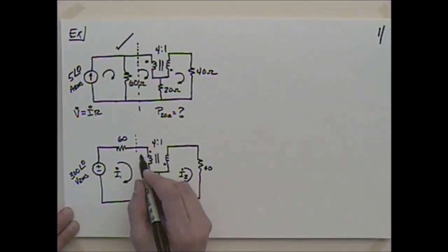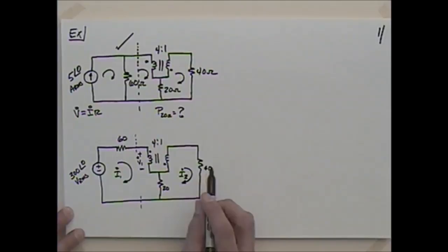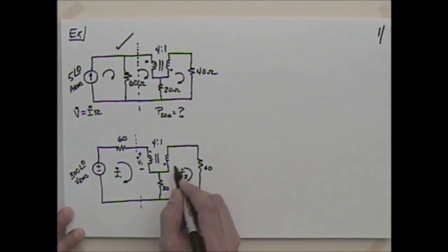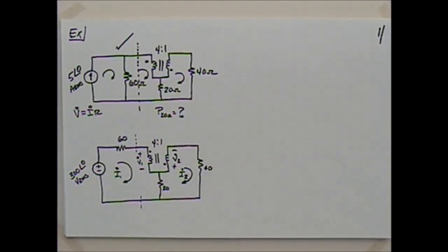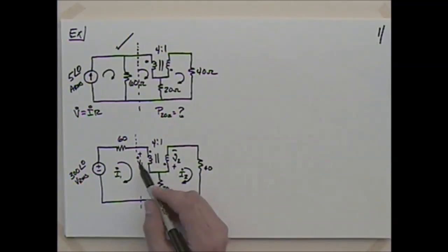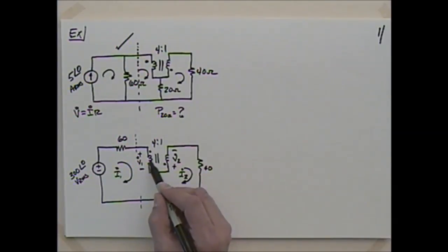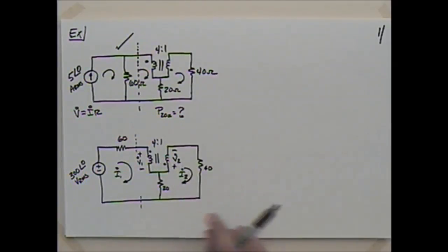So I'm going to then assume this voltage across here, I'll just assume it as V1. And I'm going to purposely make this a little bit more awkward. Maybe I will take this as V2 across here. Okay? And I can assume those voltages and currents any direction I want. I tend to assume all my currents clockwise, and then I'll just put my voltages in there. And this voltage V1 is going to include not only the self-inductance term, but also the voltage that's induced by the current through this V2 because of the coil. Questions with that so far?